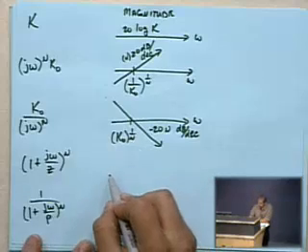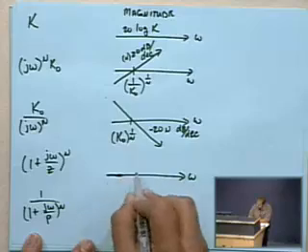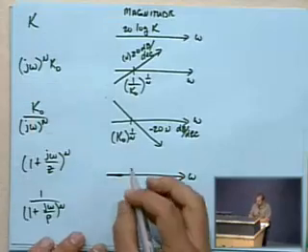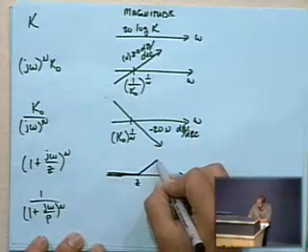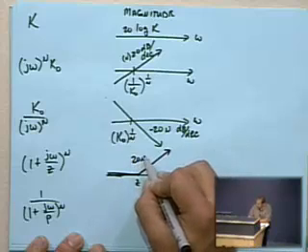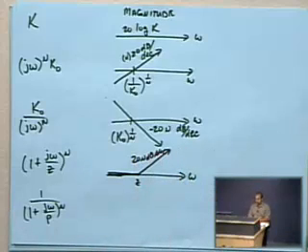Like we mentioned, a simple zero will hang out at or near 0 for a long time until it hits the zero frequency, and then it will increase at 20 times n dB per decade. So a squared term, for instance, will increase at 40 dB per decade. It will still hang out near 0 up until that break frequency z, and then shoot up at the appropriate slope.